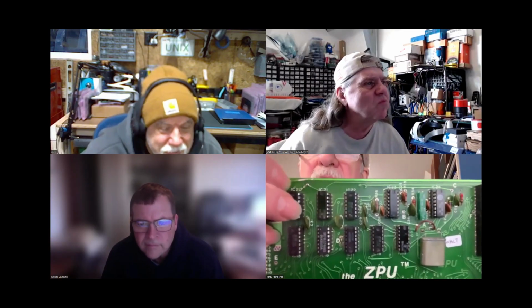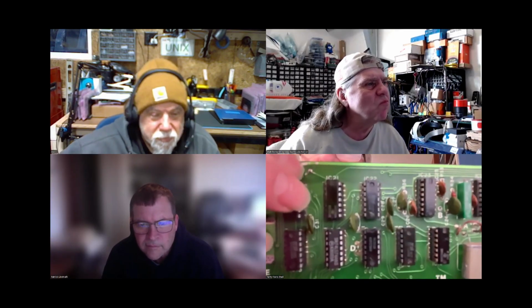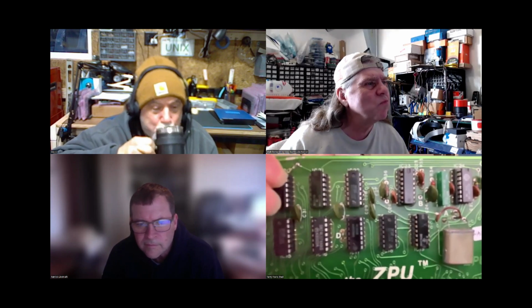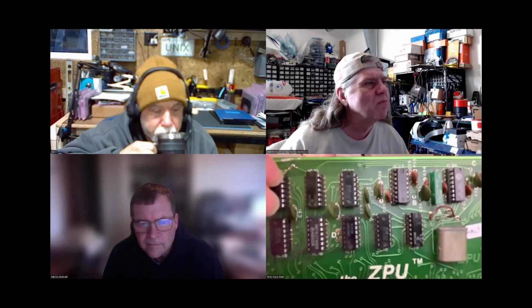Yeah, I've come across boards where things aren't working right, and you always find out that one of the pins has been pulled out, so it's not in the socket. You have to look really close to catch something. Oh, okay, there we are. Now we know what they're doing. It also looked like this trace was cut between here and down here. So I put a little jumper across that, soldered that to make sure.